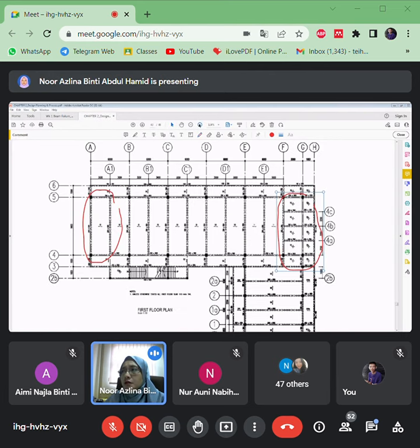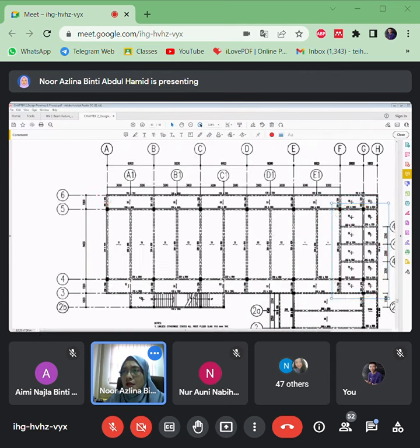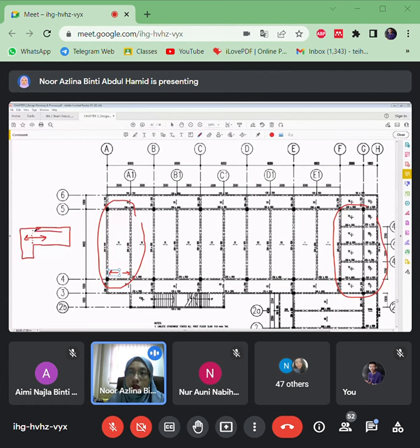I make it bigger. You also have the slides, right? Okay, you see this is all the dotted line. The dotted line means the slab and beam are connected, cast together, concreted together. There will be load distribution from the slab to the beam. So that's why it's dotted here. Let's say this is a slab, this is a beam. So dotted here means it is continuous between the slab and also the beams. Okay, so the slab will distribute the load to the beams.